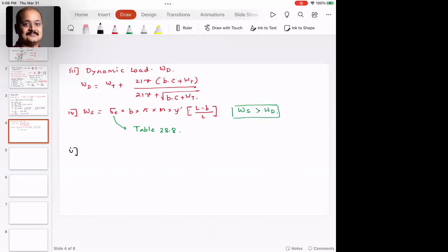Next step is we need to find out WW, which is always done for the pinion, which is the wear load, equals dp times B times Q times K. Small change to this equation. This is going to be divided by cosine of theta P, where theta P is the semicone angle.